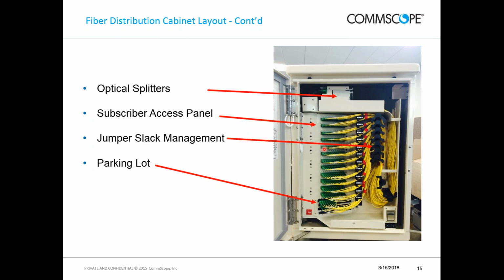Okay, and then any unused outputs from an optical splitter that's located up on the top can be set down below what we call a parking lot. And all that does is keep the fiber connector protected and clean while it's not in use.